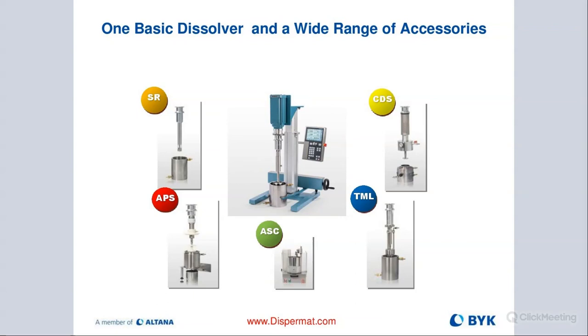So our dispersers, the Dispermats, they're well known in the industry. They have one key advantage, that they're all modular. So you can see our clamping device on top, the clamping ring. You remove it, you turn that assembly 180 degrees, and you can basically pull out the shaft and then replace it either with the rotor stator, with the vacuum system, basket mill on the bottom right. We have a wall scraping system or vertical bead mill. Excellent solutions for lab space, and means you only need one piece of equipment for many different types of milling or dispersing formulations and requirements.